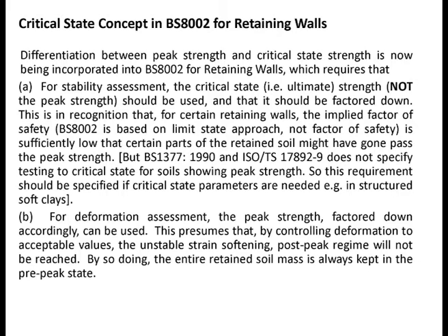So this is the first requirement. The second requirement is deformation limitation. Not deformation assessment, that's actually the wrong word. Actually, it is limitation to restrain deformation. That really is a serviceability limit state, to make sure that the deformation, the ground movement, is not so large as to cause damage to the neighboring structure, the retaining wall, or what have you.